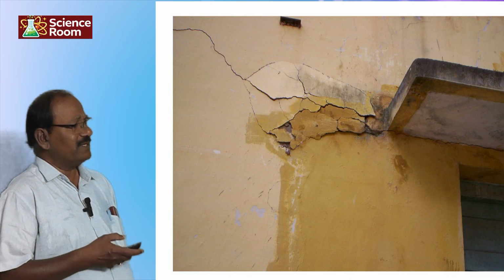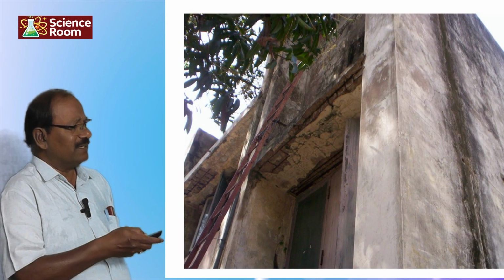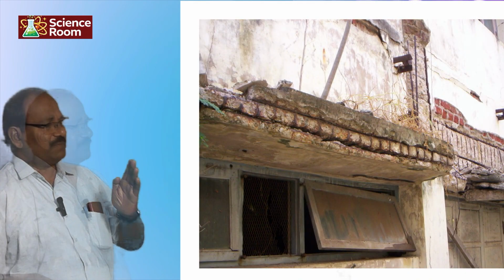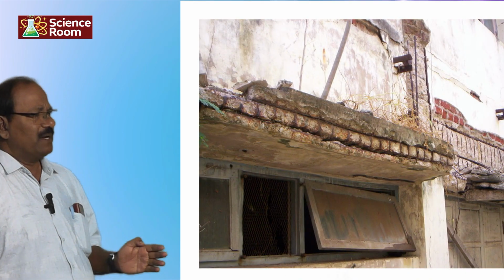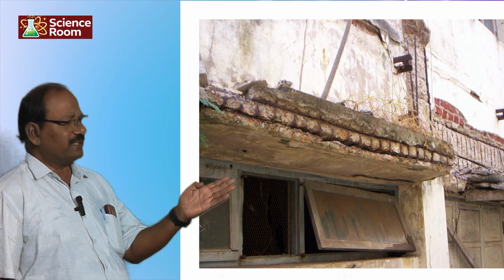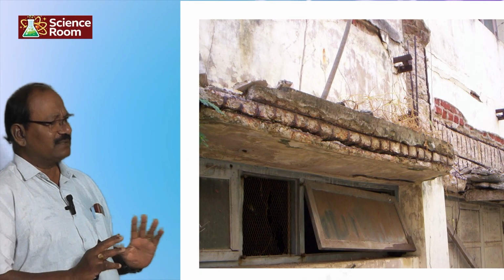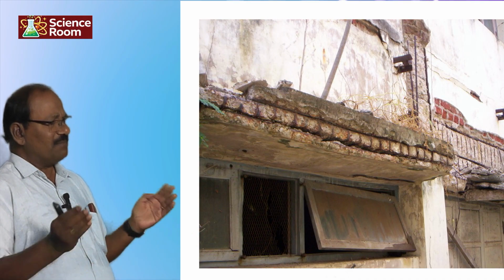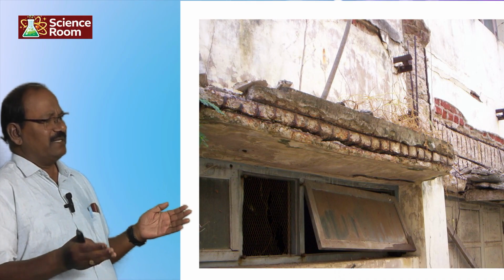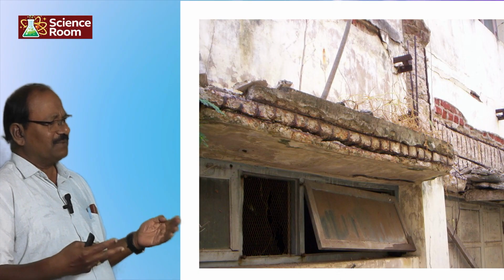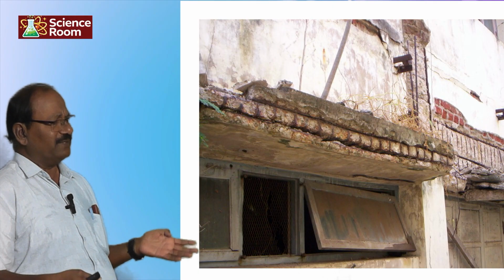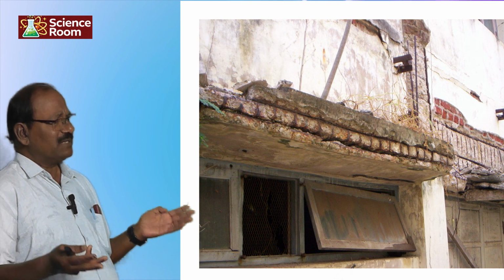Third one, you see the bottom of the slab is deteriorated and falling has taken place. The stirrups are exposed outside. The stirrups here, the sunshade, and on the other side the beam stirrups, everything is deteriorated because of the fumes that have come from the industry. These are corrosive gases, which consist of chlorides, sulfur, carbon dioxide, sulfates, all these things that come and attack this.